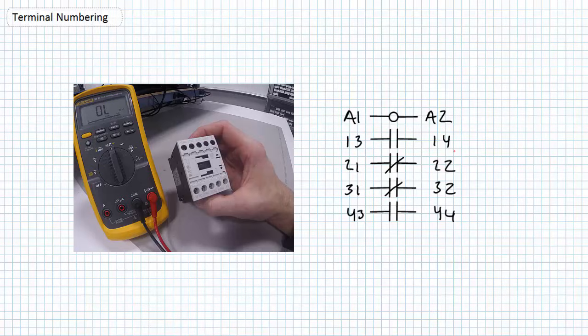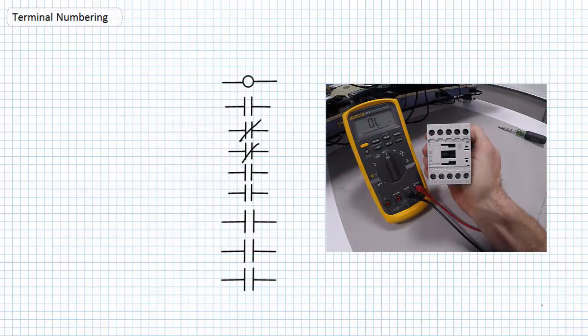When the coil of the relay is energized, the normally closed switch is open and the normally open switch is closed. Similarly, a contactor is characterized by a set of primary contacts that close when the magnetically linked coil is energized by pilot voltage.